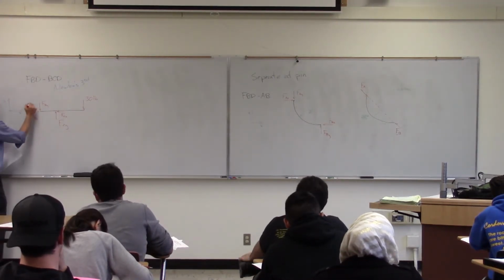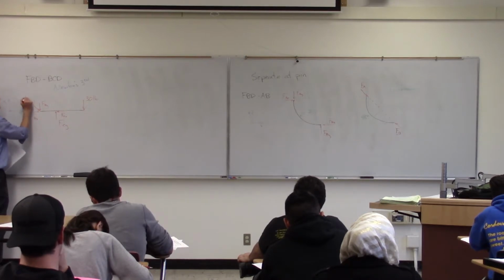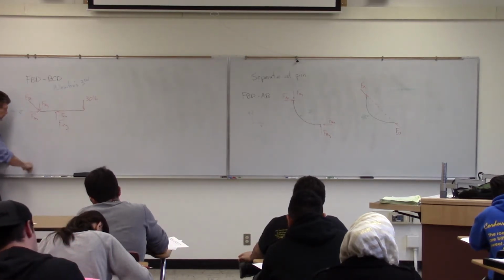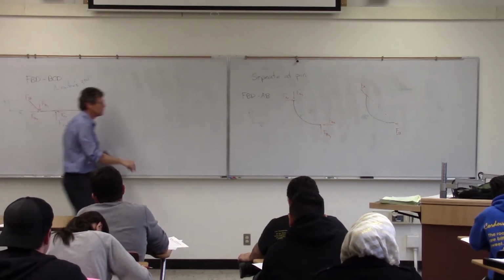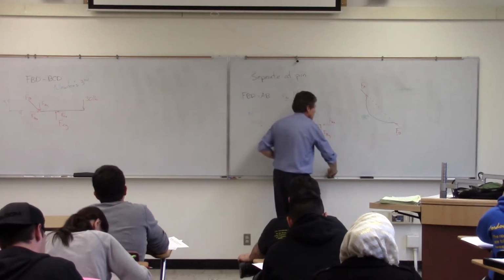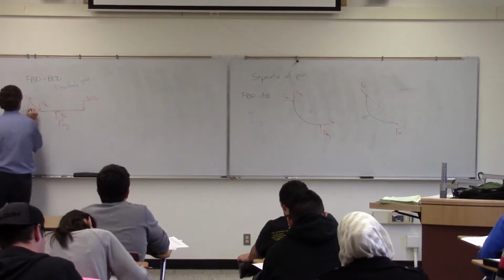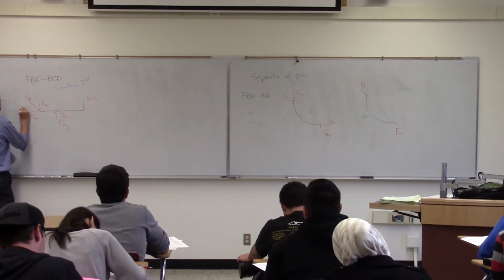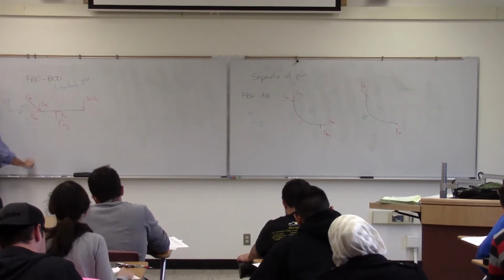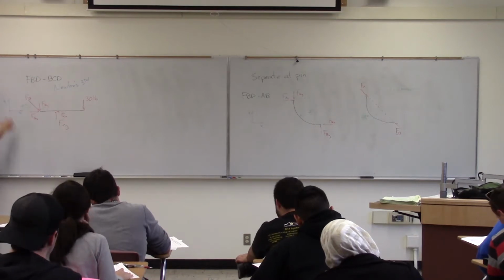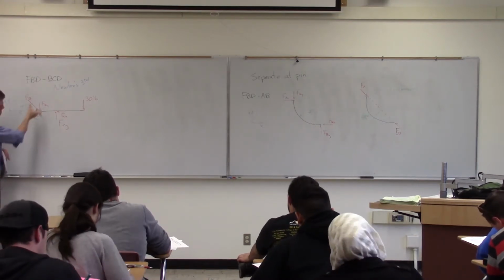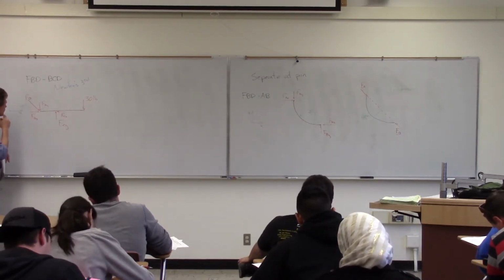But realize, looking at that other structure there, that we've established the direction of that already because I know it's a two-force member, which says Newton's third law has got to apply here too. I know my force is going to be acting that direction or the other direction. We're not sure, but it kind of looks like it'll be acting that way.